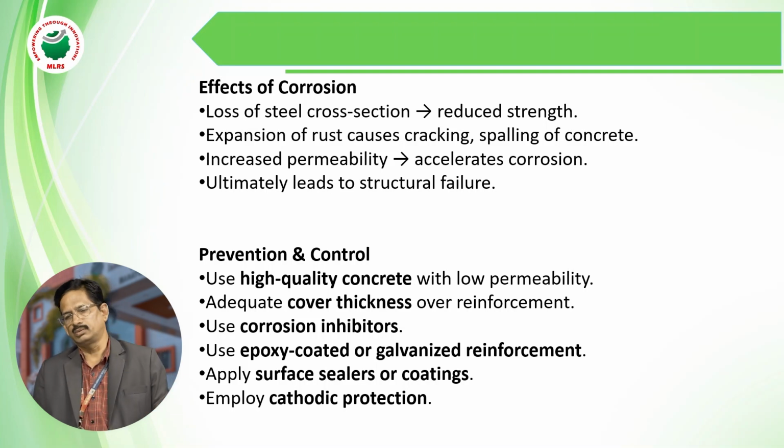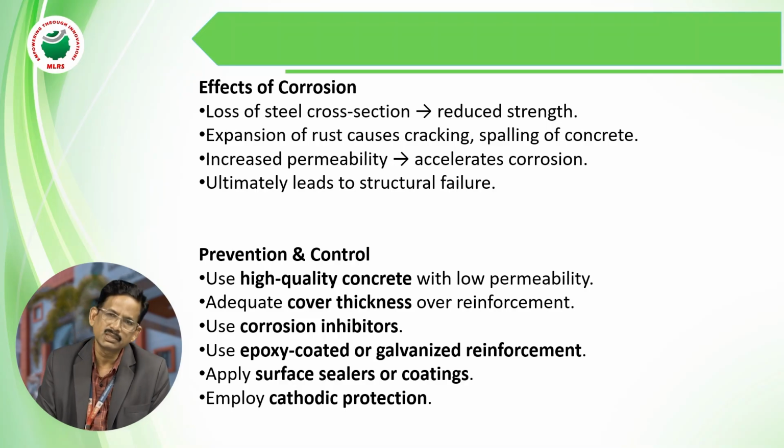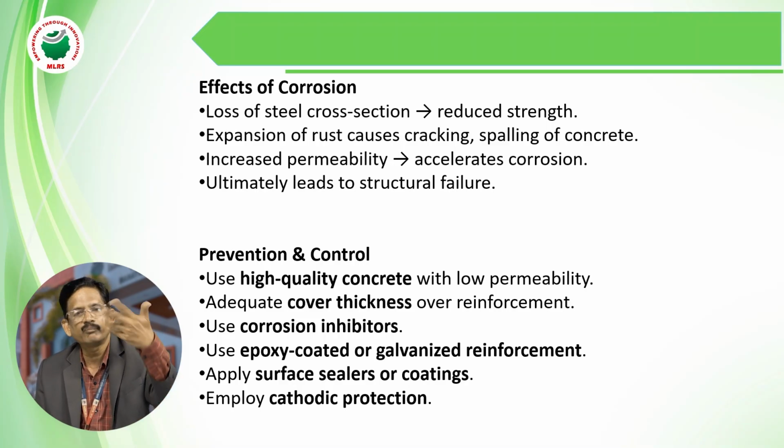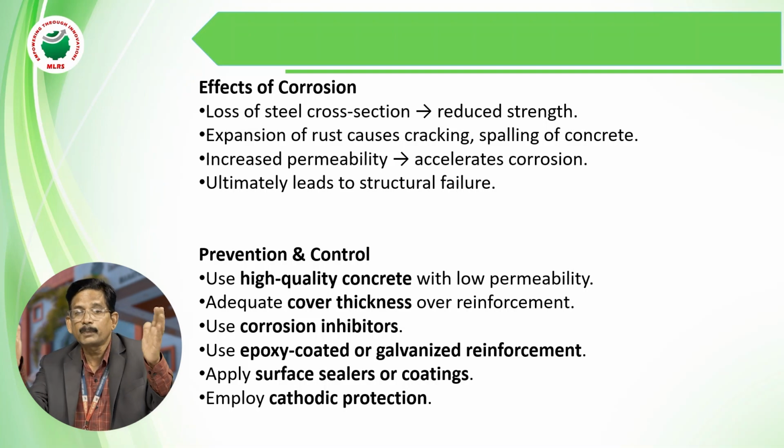And prevention and control. I think you have the doubt: what are the preventions, what are the controls? Use high quality concrete with low permeability. Permeability is also very, very important. What is permeability? The flow of water particles through the concrete itself. That is also why we design high strength concrete, if you go for M30, M35, M40, M45, M50, with low permeability. Permeability is nothing but the flowing of water particles within the concrete. Is it right or not?